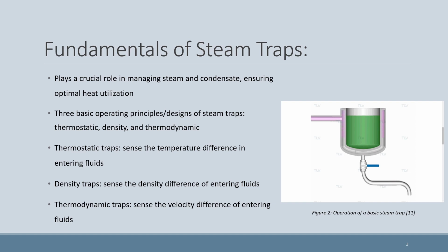When steam enters, the product inside the jacketed kettle is heated. When steam does its work, it condenses and becomes condensate. The heat transfer surface area grows smaller as the condensate builds up, so the condensate must be removed. Removing the condensate by merely opening a normal valve will discharge the condensate, but steam may also be discharged, which we don't want. A steam trap will discharge only condensate, while preventing any leakage of steam.